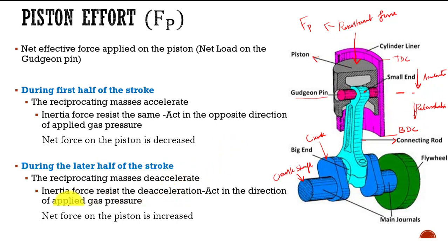So at the end, the net force on the piston is increased, because during the retardation the gas load applied on the piston is multiplied by the action of the inertia force.